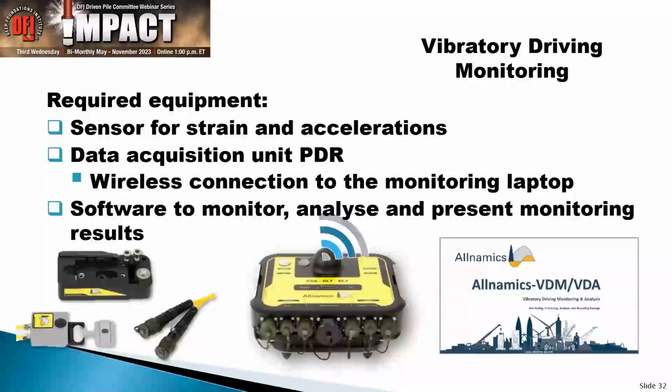So we've done the prediction. I showed you how that works. Basically the same thing that you're doing normally. And then it comes, okay, how do we go from here during the monitoring? And again, it's very familiar. You basically have a strain gauge and accelerometer, sensors for the strain and accelerations, just what you used to with monitoring during impact driving.